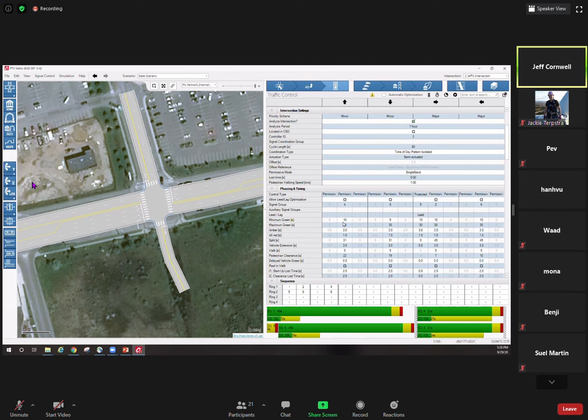So once you guys have done that, you can then fill in this information. Min green. You can leave max green at 30 for now if you want. So fill in the min green, the amber time, the all red time, and leave the split alone for now. Then once you've done that, you can add the extension time, walk time, and ped clear time. So I'm going to start doing that myself.